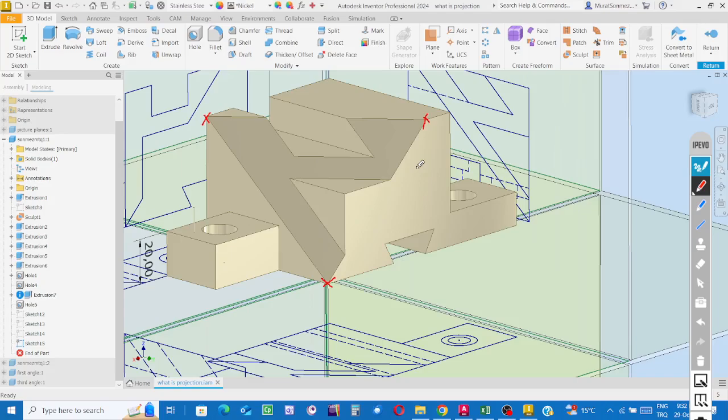In the AutoCAD environment, to create an oblique surface, we may have two different cases. If the oblique surface is to be created at a corner where the surfaces are perpendicular to each other, then we can start the polyline process, but first locate the origin of the coordinate system at the corner.